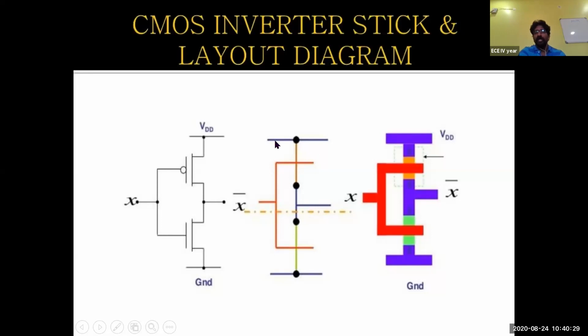Similarly, this is a power rail and this is also a power rail. This indicates the VDD, the main supply, and this indicates the ground, which is the low supply, almost equal to 0 voltage in our case, and this is a high voltage. Since these power rails have been drawn with metal layers, we can either drag the metal upon the P diffusion, or drag the P diffusion upon the metal layer. Either can be done, but wherever you make the connection, you should put a contact in order to make an electrical contact.